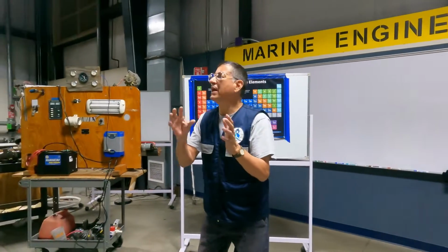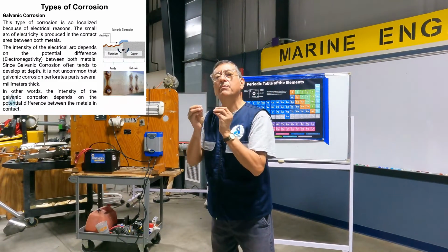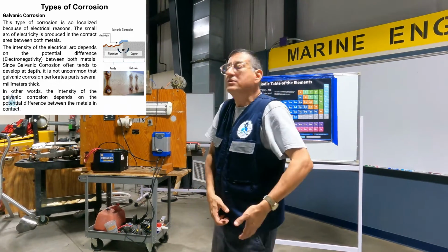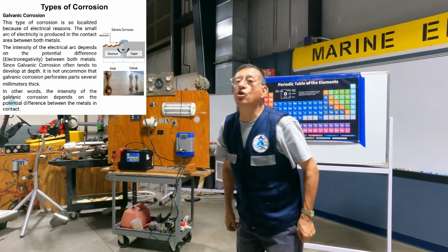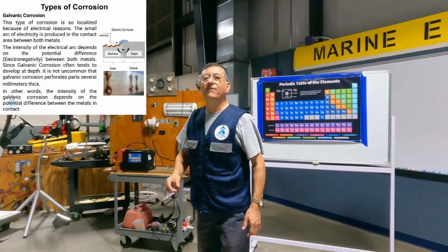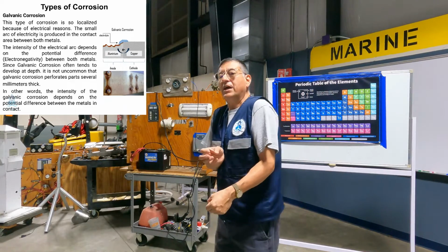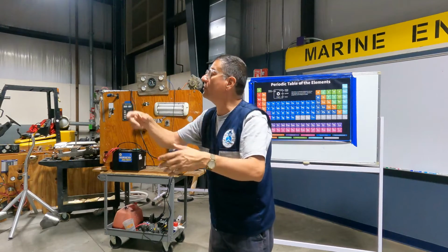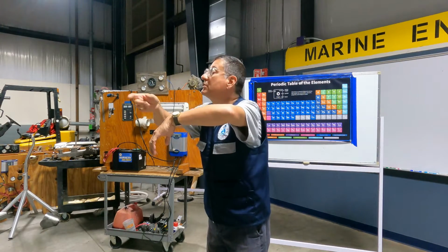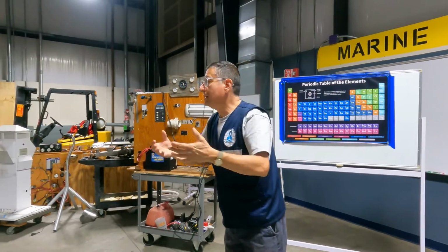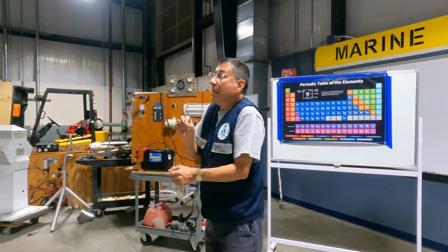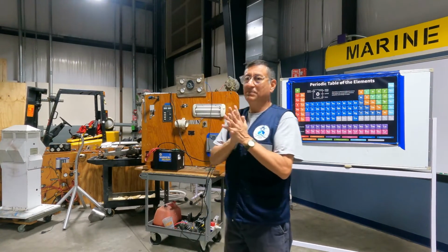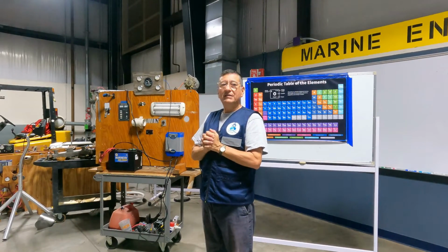What is the name of that corrosion when you have 2 dissimilar metals together in a marine environment and the element with more energy attacks the element with less energy? Galvanic corrosion. And what happens if you have that situation, 2 dissimilar metals together, and additionally, for some reason, internally in that refrigerator, one cable with power is touching the housing? You have electrolysis, because you have galvanic corrosion plus current, and the current accelerates that process. This is part of the corrosion course, but this is later.